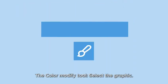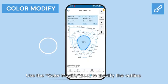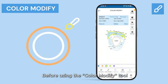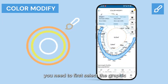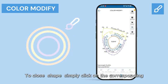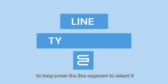The Color Modify tool: select the graphic. Use the Color Modify tool to modify the outline color of the graphic. Before using the Color Modify tool, you need to first select the graphic. For a closed shape, simply click on the corresponding graphic to select it. For an open shape, you need to long press the line segment to select it.